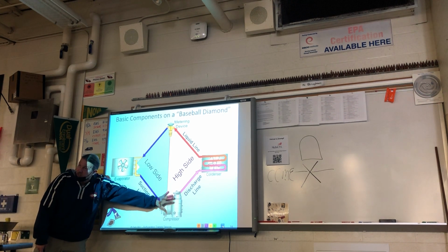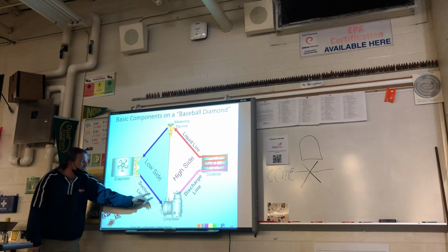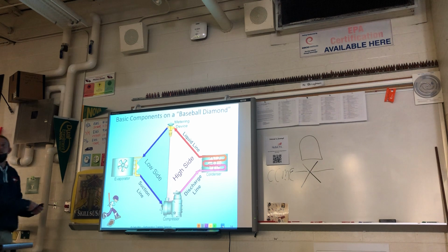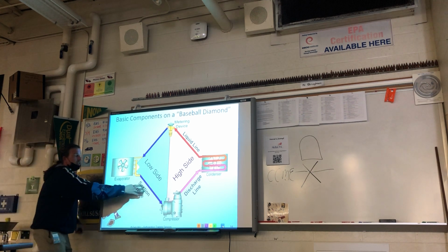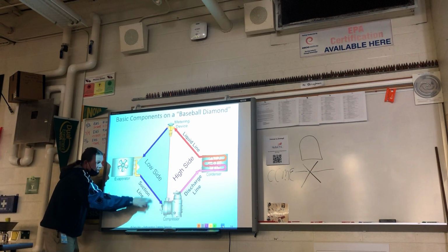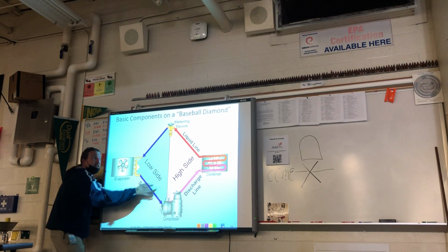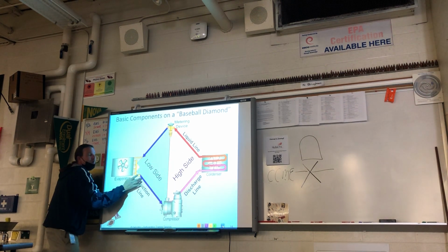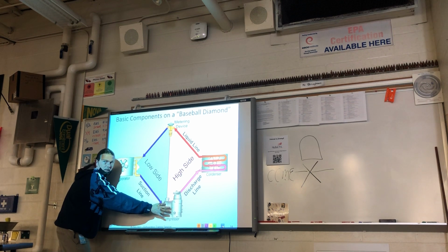Because if this compressor gets liquid, which is the whole purpose of this accumulator. The accumulator, I used to have it right here and I used to be able to grab it. I don't know where it went. But the accumulator, the word of the day today, is the piece of the device that acts like the receiver on that end that only feeds liquid to the metering device. We only want vapor going back to the compressor.